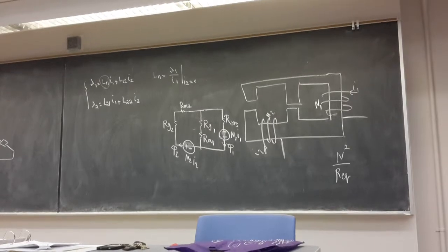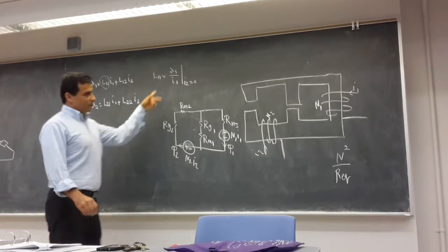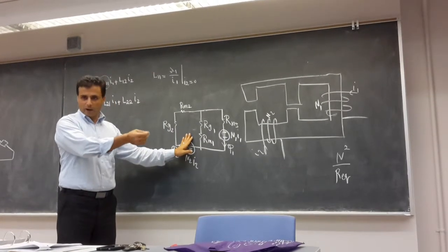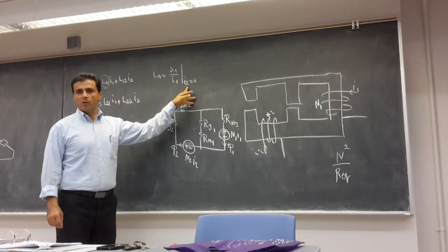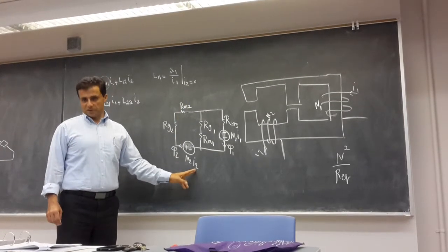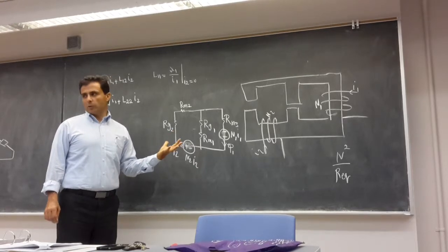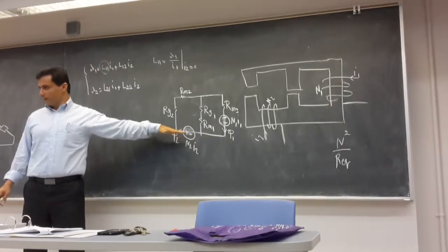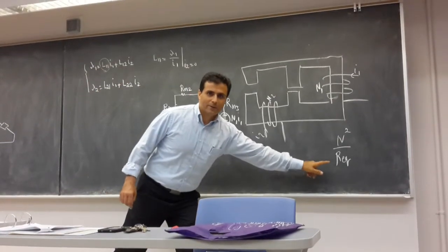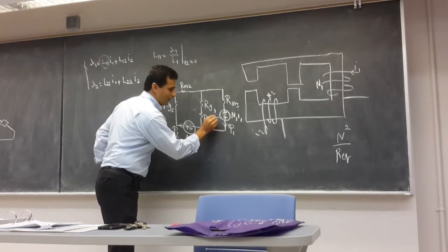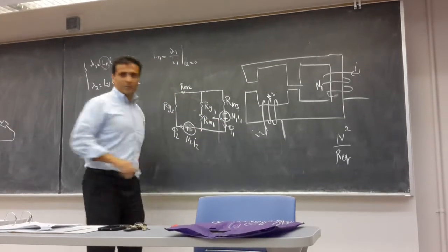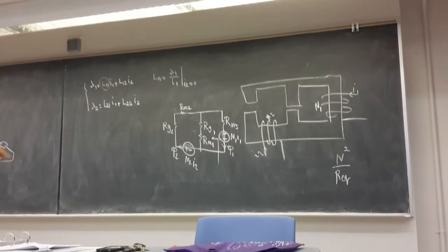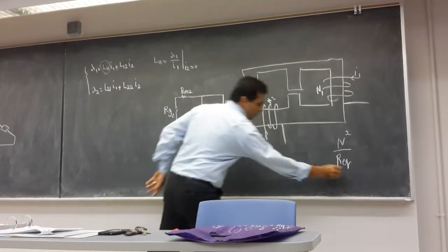Now, I'm saying if I want to calculate my L11, forget this one, just short it, right? If I say I2 is equal to 0, N2 I2 is going to be 0. When a voltage source is 0, what does it mean? It's a short, right? So basically put a wire here. How much is the R equivalent now? I need to look at it from here. Remember from circuit theory, the Thevenin resistance. Can somebody tell me how much is the R equivalent here? Let's call it ReQ1.